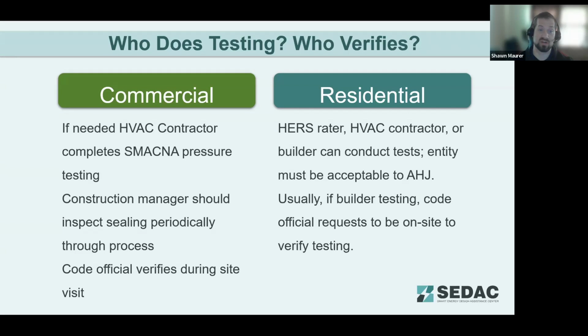As far as the pressure testing results, usually that's going to be the rater who's come out to the building. They'll do that test, supply a report. The report needs to have the duct leakage results with a signature on the form. We have seen a couple of those forms come in without a signature on them, in which case it would not be in compliance with the verification requirements for the energy code. So you do need to have a duct leakage report with the testing entity's signature on it to be qualified as properly verified for that leakage test.